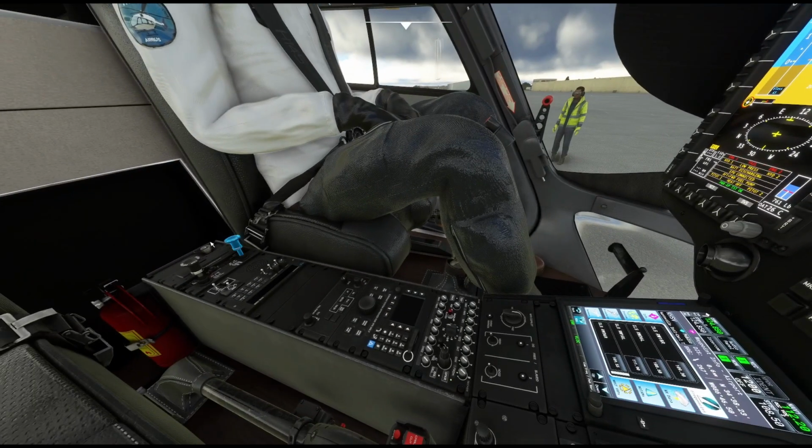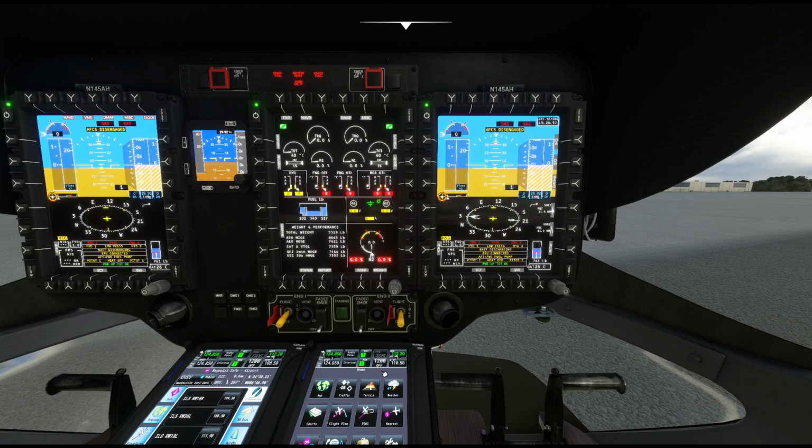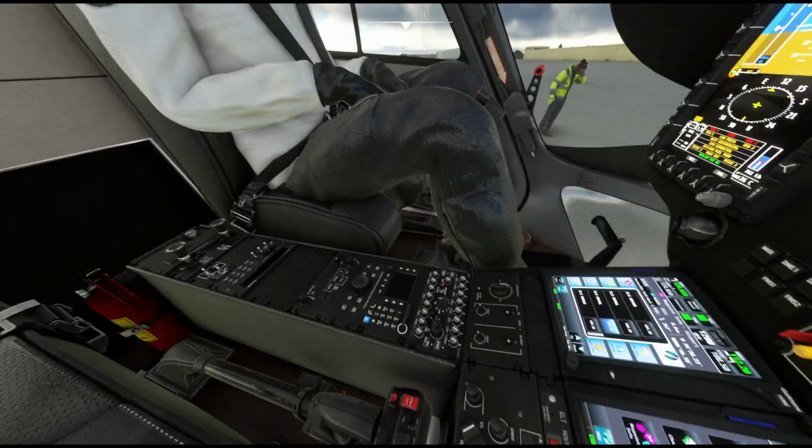So at first power up, this time right here is loaded into AMC2 and pushed forward to MFD2. And then after about 34 seconds, the time is updated in AMC2 via this and pushed to there. And then simultaneously, it updates the time inside of the data transfer device back there.